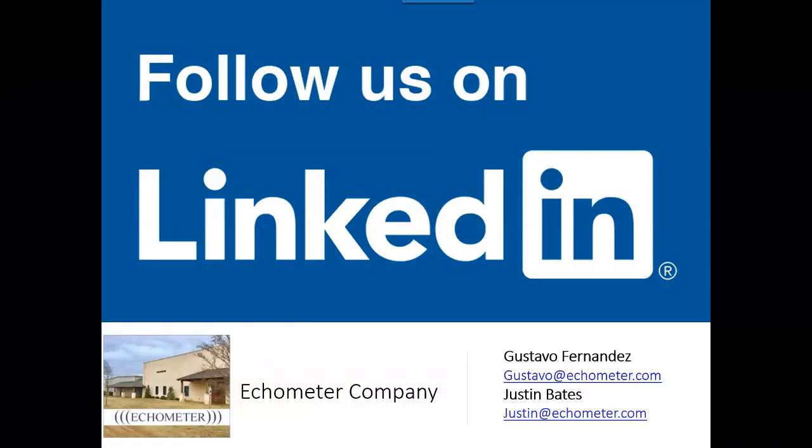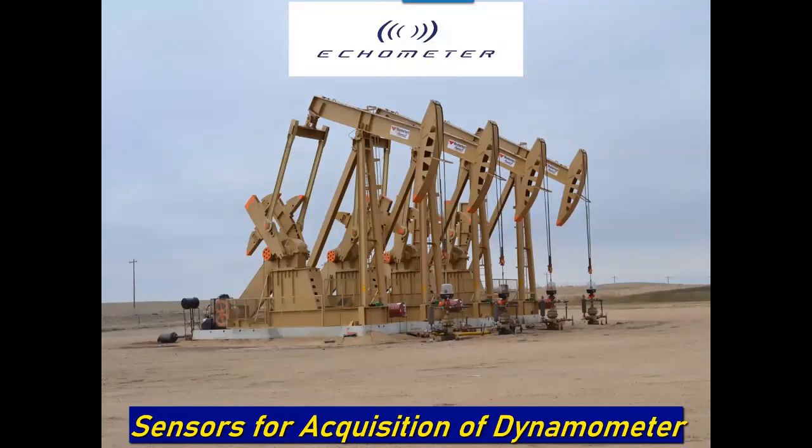Without further ado, let's get into the presentation this morning. The way I felt we should structure this conversation on dynamometer data is that before we get into dynamometer interpretation, you need to understand what sensors to use, and when you would want to use those particular sensors to acquire that dynamometer data. Echometer makes several different dynamometer sensors, and they're all great, but they all have good applications for when they need to be used. During this presentation, I'm going to introduce the individual sensors. I'm going to talk about the pros, the cons, and when you might want to use that particular sensor, and build the framework for the fundamentals, which will be discussed when Gustavo speaks in a little while.